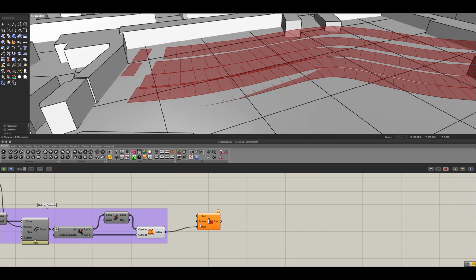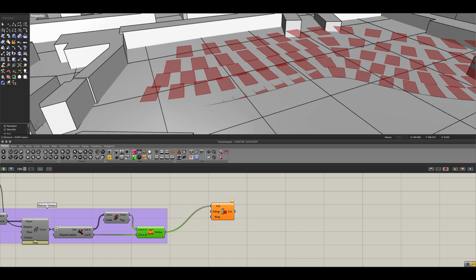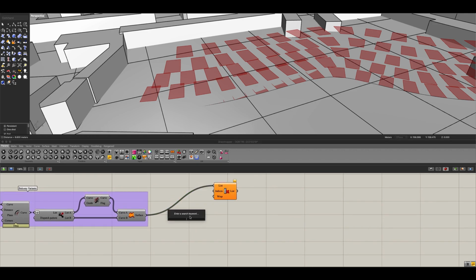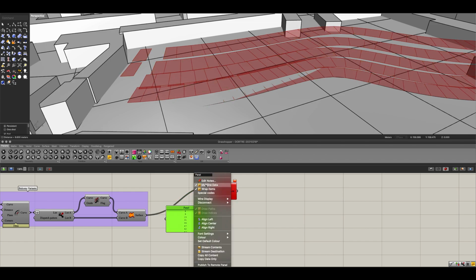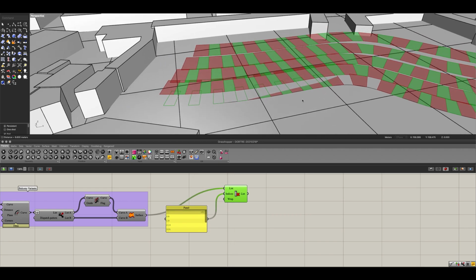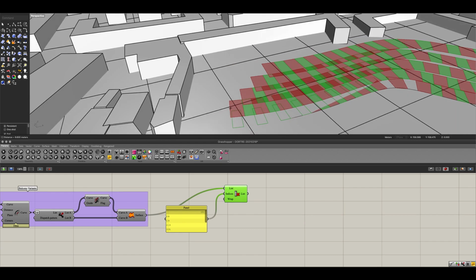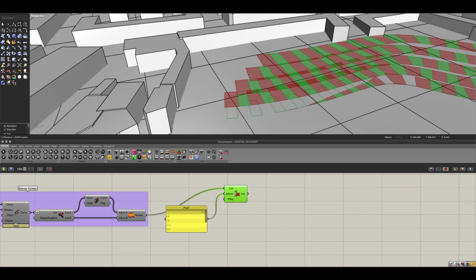In reality, this is something that we need to check in manually and see which ones fit and which ones don't. So let's scatter in a col index. Let's put this one out like that. And now let's add in a panel. And for the values, the ones I figured that work here are the 8th, 9th, then we have 15, 31, 46, 47, 62, and 63. Multi-line data. Now, as you can see here, we now have the available and visible planes to make our stair effect. Therefore, removing these ones here.